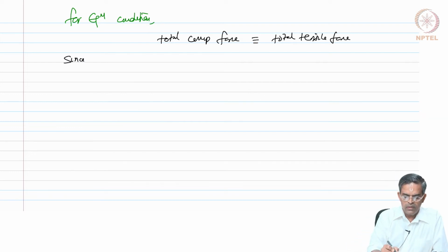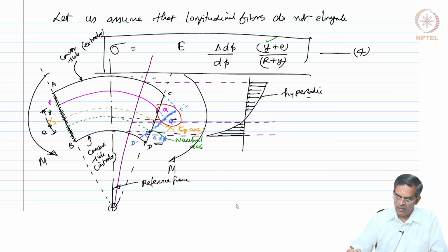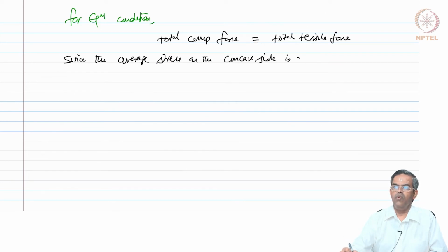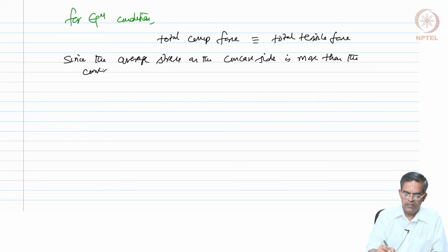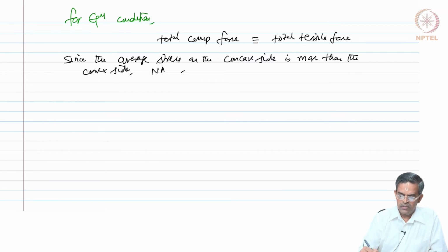Since the average stress on the concave side is more than the convex side, the neutral axis shifts towards the center of curvature.